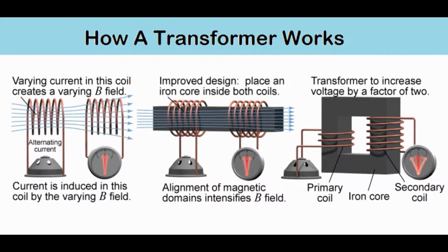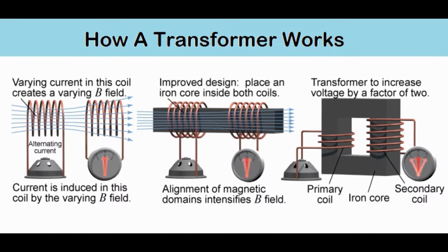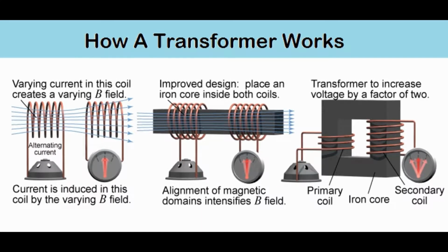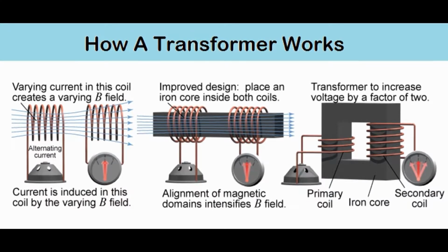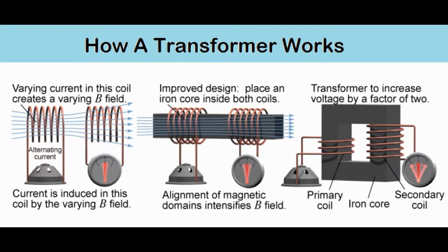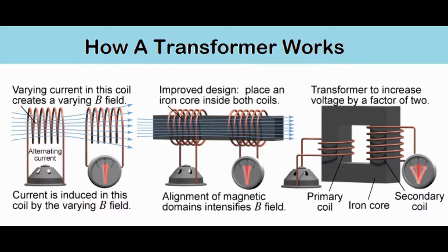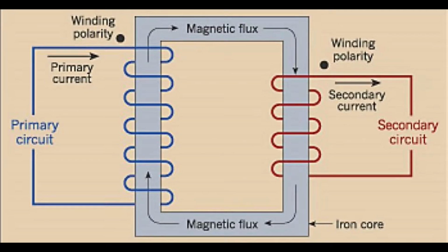It is important to remember that transformers do not generate electrical power, they transfer electrical power from one AC circuit to another using magnetic coupling. The core of the transformer is used to provide a controlled path for the magnetic flux generated in the transformer by the current flowing through the windings, which are also known as coils.